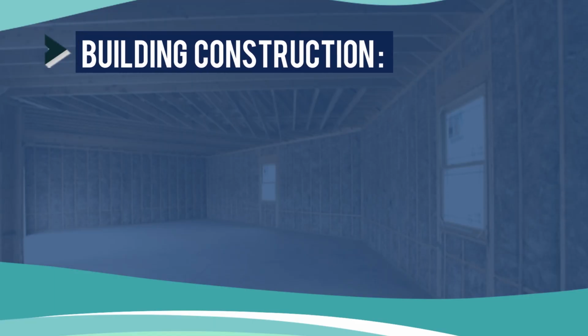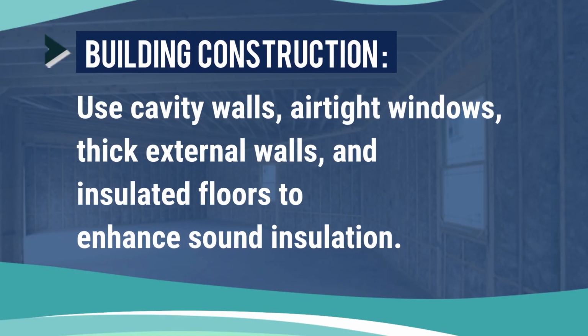Then the sound insulation. Sound insulation is increasingly important due to rising population densities, changing community habits and increased noise pollution. Effective sound insulation reduces unwanted noise transmission through building components. Building construction: use cavity walls, airtight windows, thick external walls and insulated floors to enhance sound insulation.